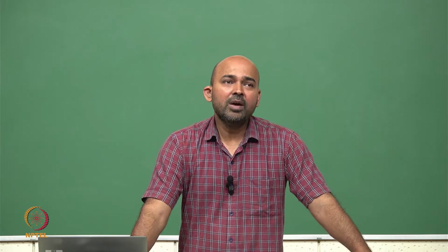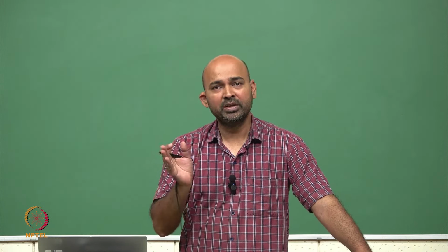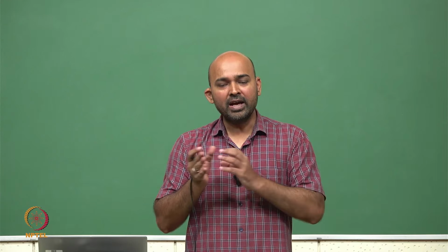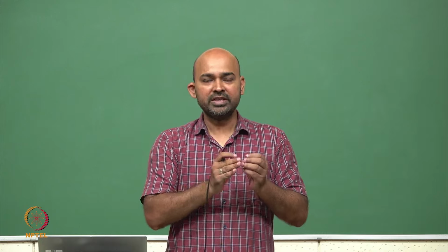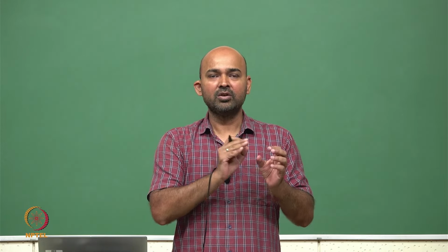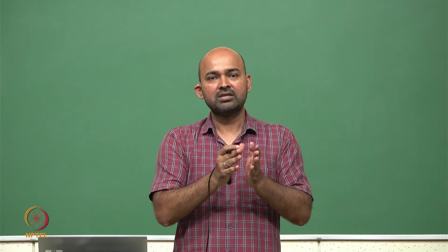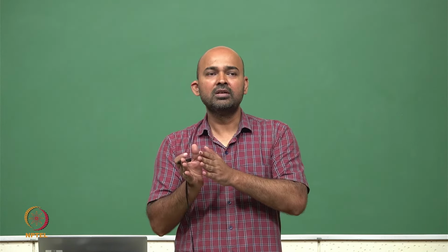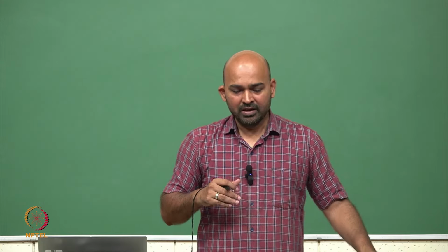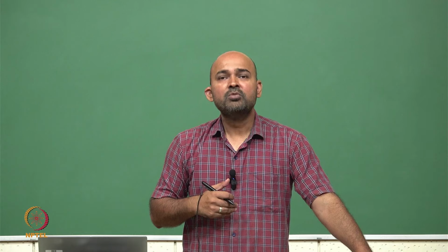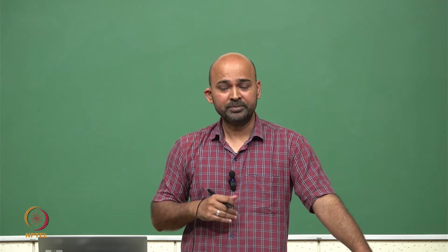So, that we can do by DC simulations, where we are sweeping the voltage or sweeping any parameter without any knowledge of time. So, there is no change of time for a circuit, only the change of a parameter. Temperature is only changing, there is no information of time in the DC simulations. The next type of simulations are transient simulations, which we are going to discuss today.